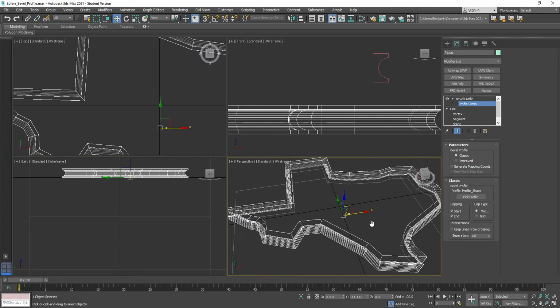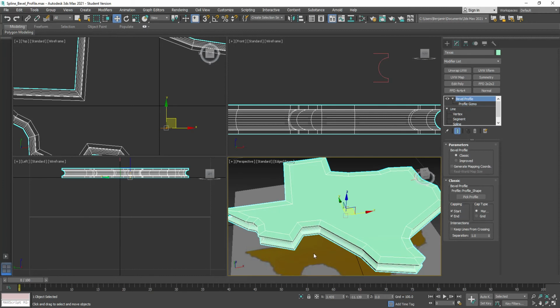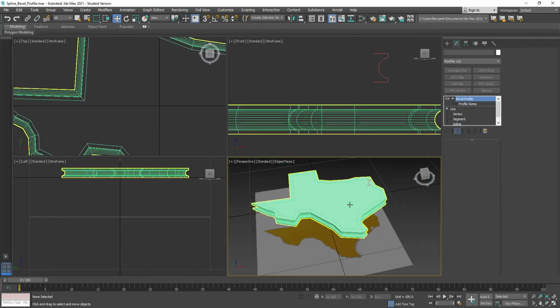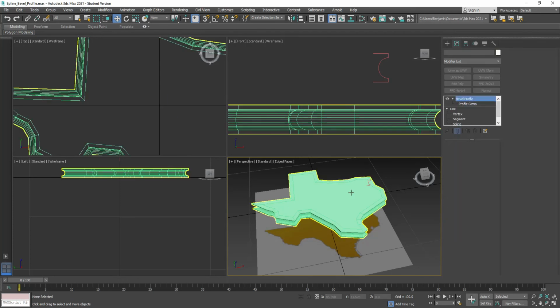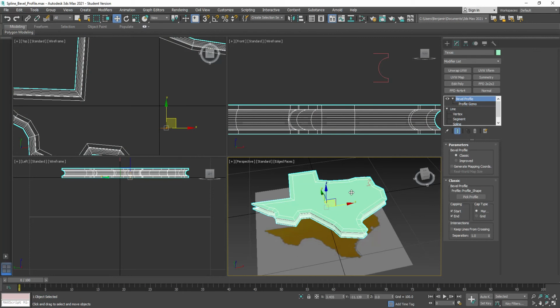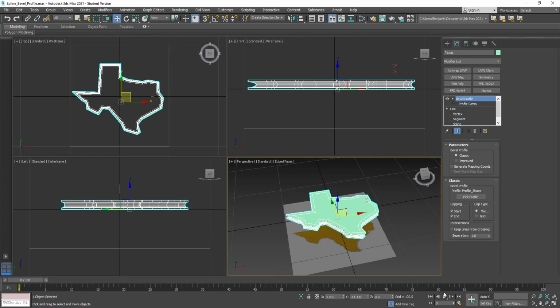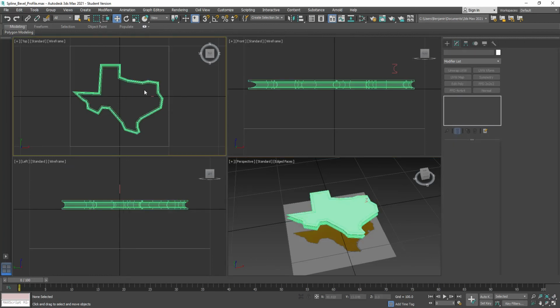Now this all worked out very well, right? There were very few problems that I ran into, and I'm going to explain to you, just to reinforce, the things I did to make sure that this was a very hassle-free project. So let's go down here, not the bottommost button, but the one above it for Zoom Extents All. So first off, in the top view, I started modeling out here. I started in positive X and started drawing around to create my shape. I made sure it was not too detailed. It didn't have too many points that were too close together.